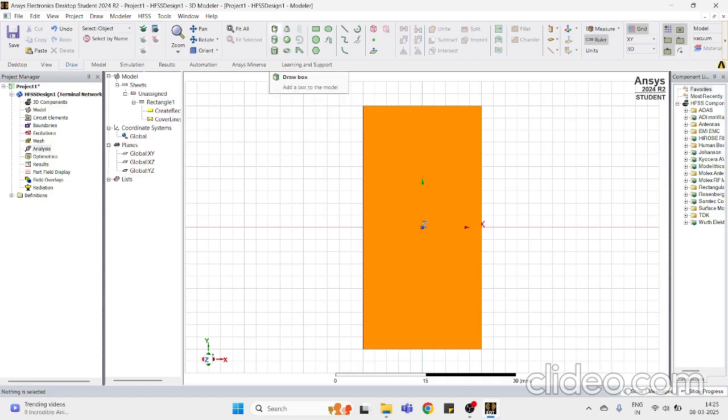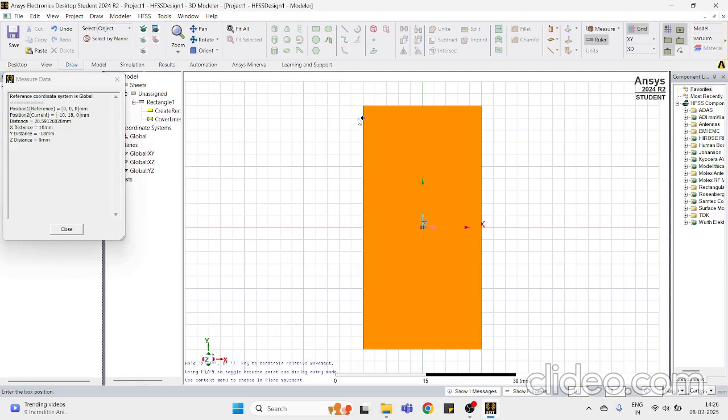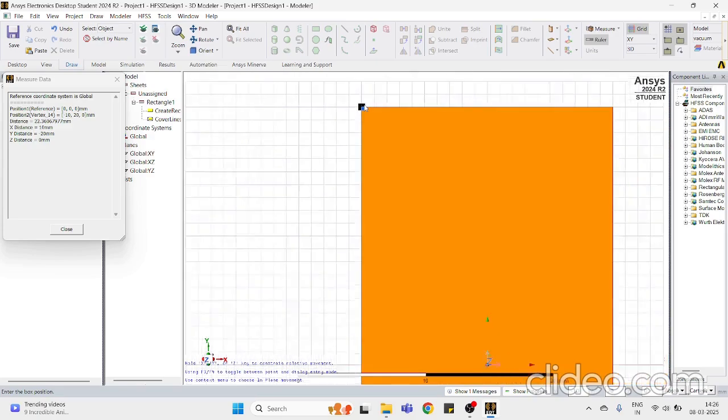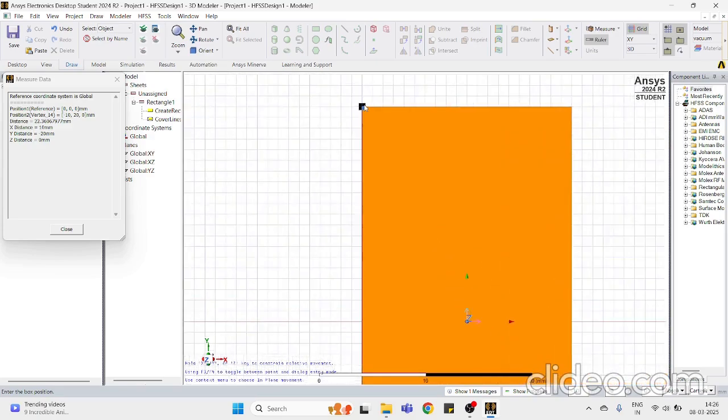So here we will be using FR4 substrate of 1.6 mm thickness. So I'll be selecting this. And now that I've already assigned the coordinates for this, it's quite easier to draw a box. So I'll just hover over this point. This is the exact point that you see, and you can always zoom in as much as you want by just using the cursor.